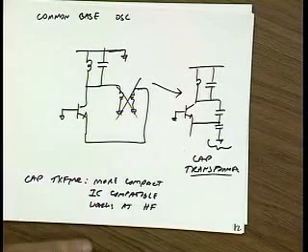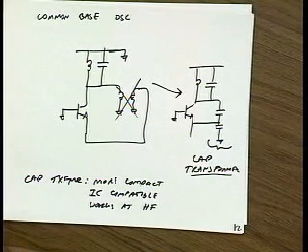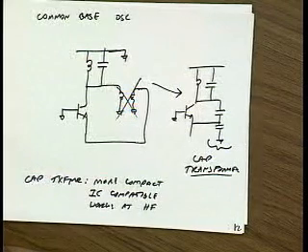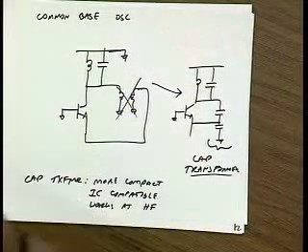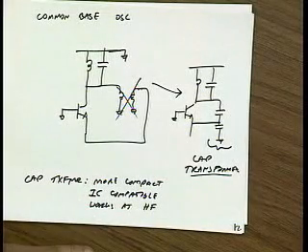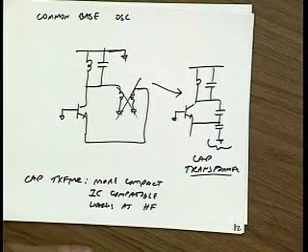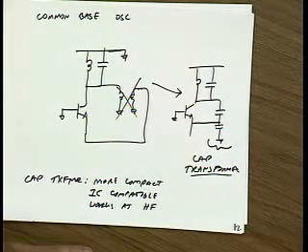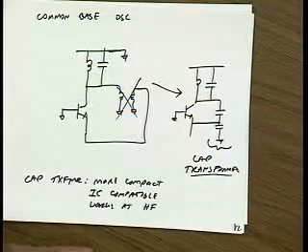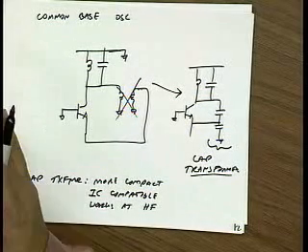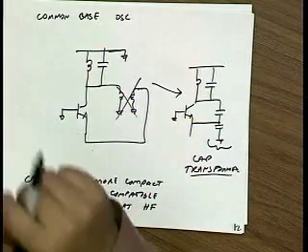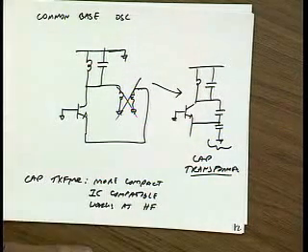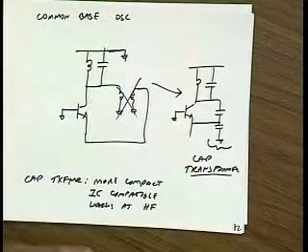Questions? Yes, Debo. So, is the transformer the only way to generate a 180-degree phase shift? Can't we hook up another amplifier, unity gain, say, which will... You could. Come up with something. Maybe we'll name it the Debo oscillator. Generally, if you're building a high-frequency oscillator, you'd like to have as few devices as possible, because of noise, we'll talk about phase noise, and otherwise because of the delay. So if there's too much delay in the feedback network, the oscillation is going to move away from omega naught.